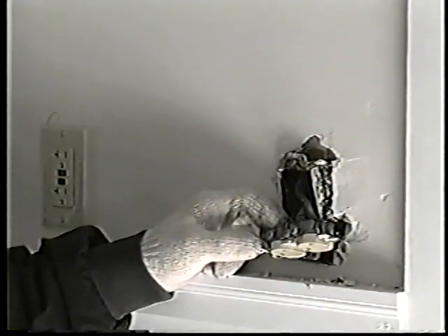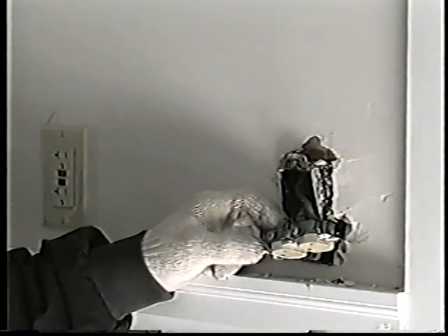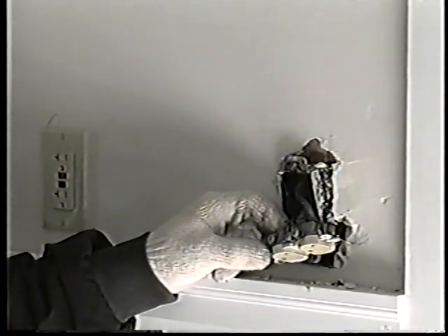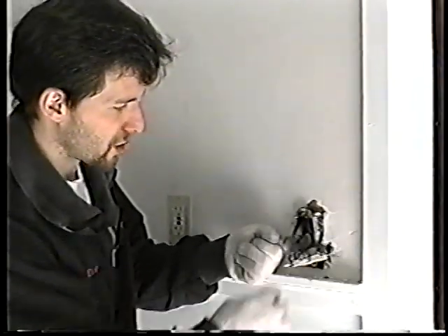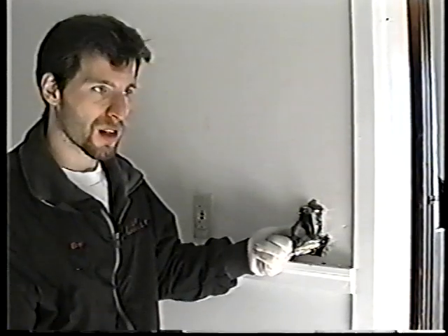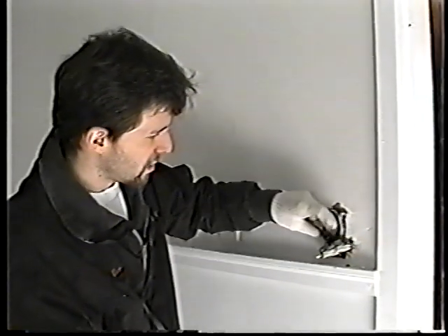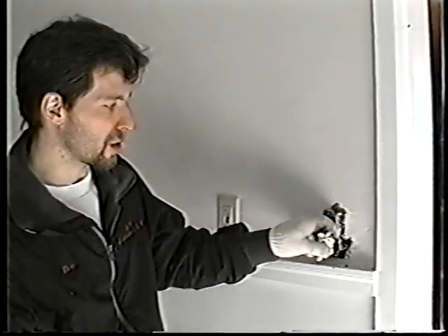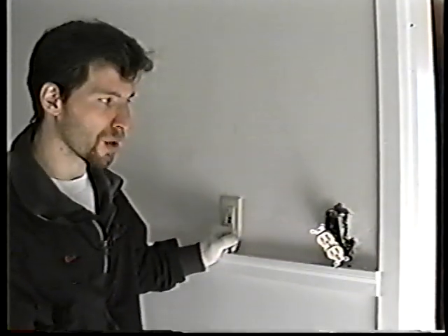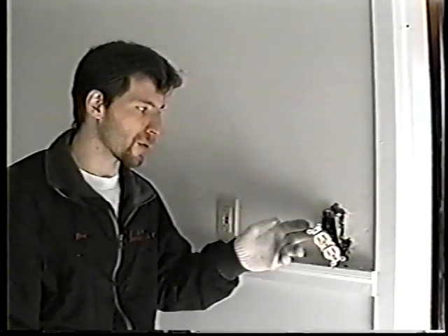This wiring, if possible, should be eliminated if it's in real rough shape, and a lot of times it is, just from old age. Back in the day, they never used to use any splice caps or anything. They just used to use tape and tie the wires in any way they could get them on there. That's a big mess right there, and on this house we are going to actually eliminate this because we have the other two plugs that we've installed now that are new.